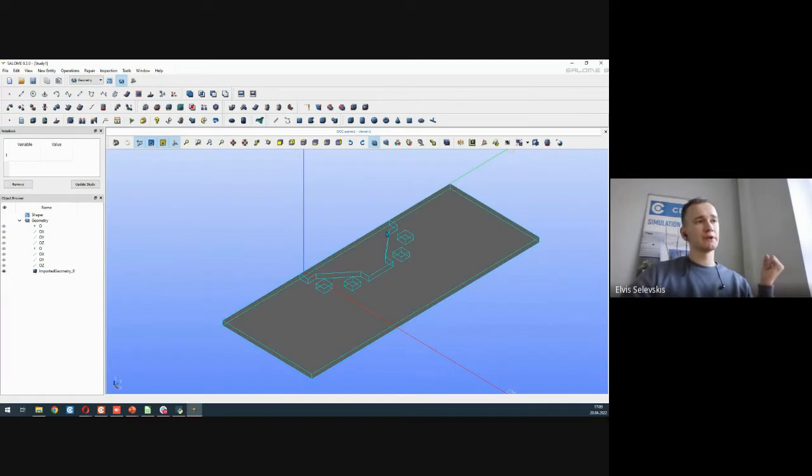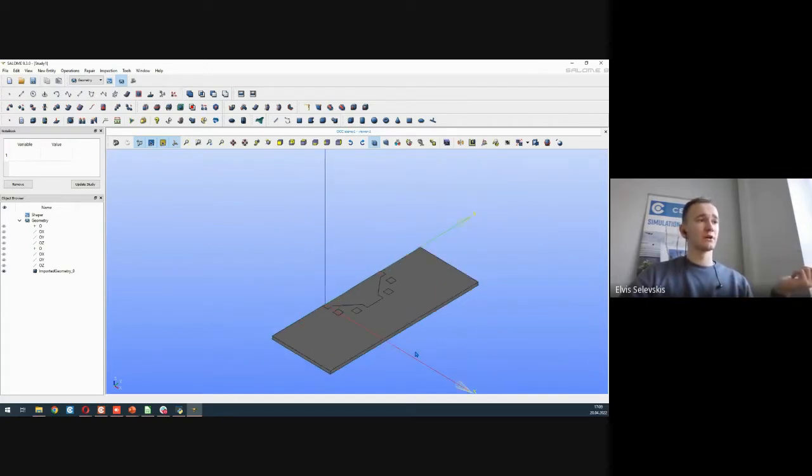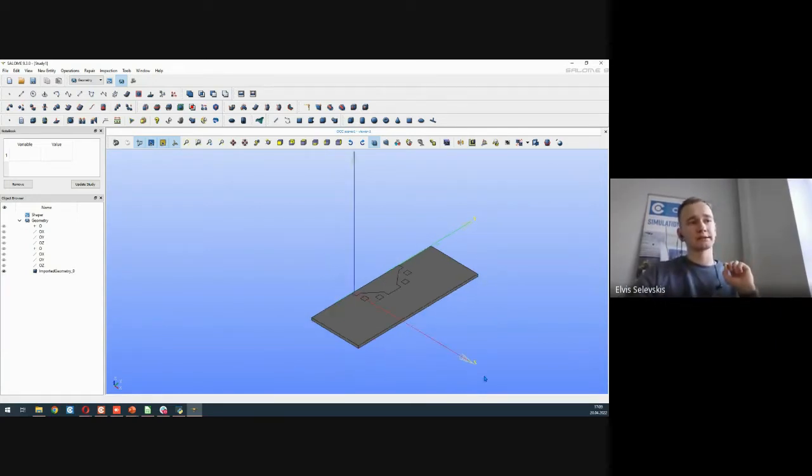So here's the workpiece. Here's one inductor winding, second inductor winding, third, fourth, and this is what we will use. One thing to mention: always when you want to position your CAD files in order to export the 2D faces, always have these faces exactly on the XY plane. That's something which has to be correct.